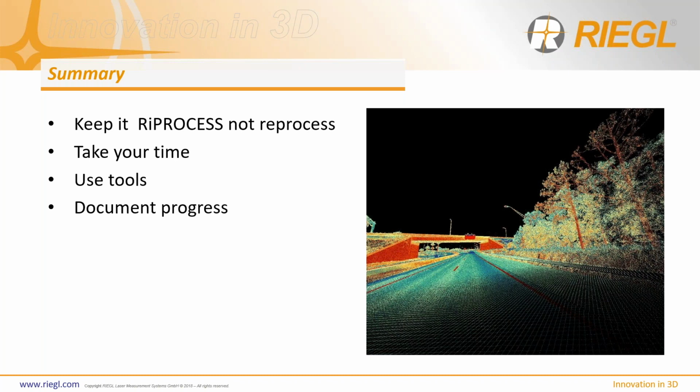Document your progress, right? If you're someone that runs RIEGL Precision and really feel like it doesn't do anything, but you don't have the before to compare the after, why not? You gotta help yourself out. It's really hard to visualize or remember what a quick look at the raw data looked like without having a before image. Now, obviously, you're not going to export the LAS files and do a differential between every one of them. That's a lot to ask of you. But doing a simple check would be very advisable, in my opinion.